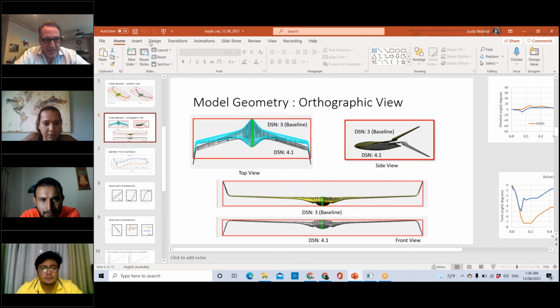But those are all easy. Those are logical steps. That's something in the big airplanes, like if you're doing a 777 or something, you design it, you fly it around. The aerodynamic CG does not line up with the real CG. So then we slide the fuselage. We just slide the fuselage on the wing until the two line up. It's a real simple process. And it turns out you often don't have to slide the fuselage a lot, just a little bit, and it'll get those things lined up nicely.